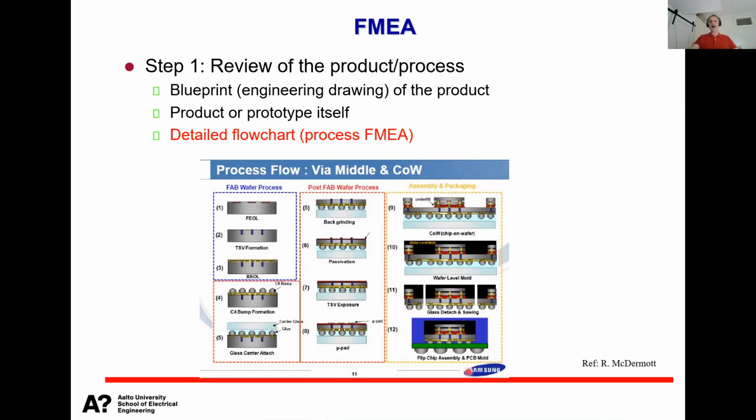So having the actual IC processor chip, the logic, together with a stacked memory chip, and this would then be assembled into your phone. And now if we think about the manufacturing process, as I said, this is a wafer level process, meaning that up to here, basically the wafer is handled at wafer level. So the processing is happening at wafer level.